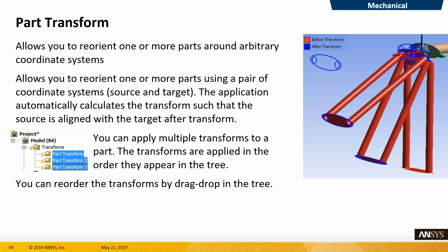It's fairly easy to use. You simply import your geometry and then you use the duplicate function that you maybe already know from the Mechanical workframe. Then you can set a parameter that could either be a rotation or translation parameter that you can then change the imported or duplicated geometries on.